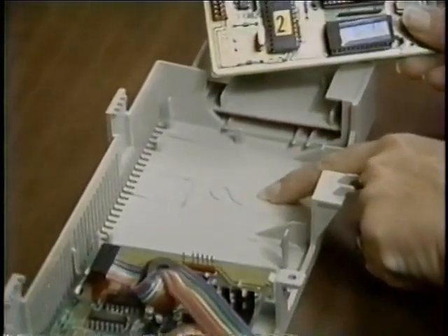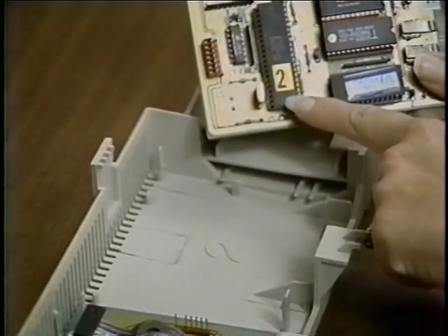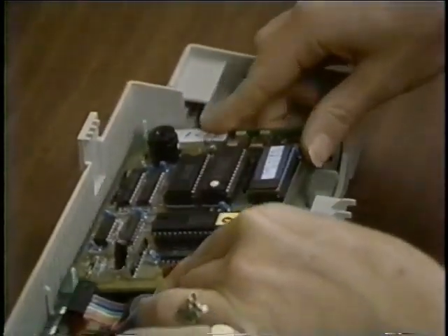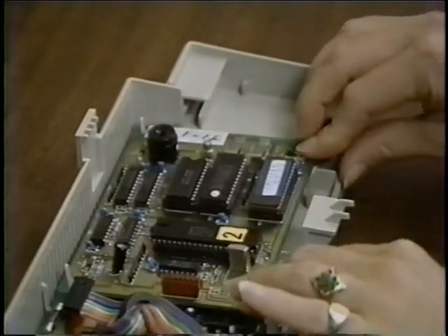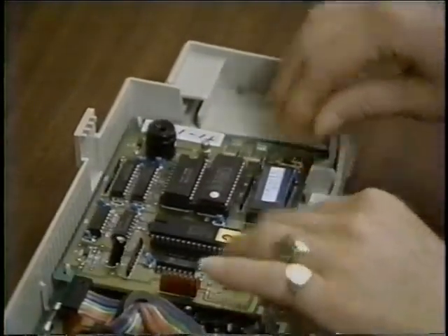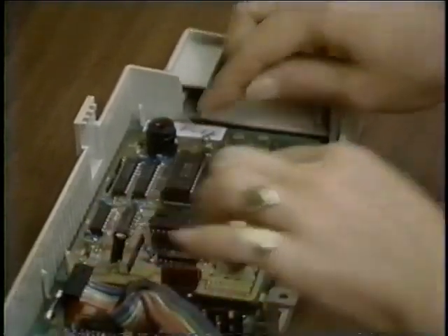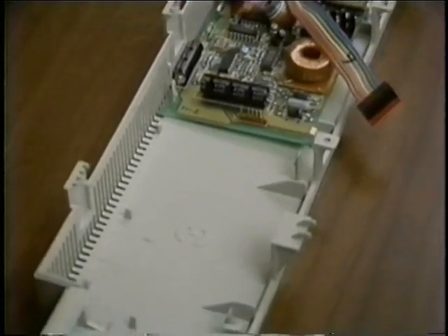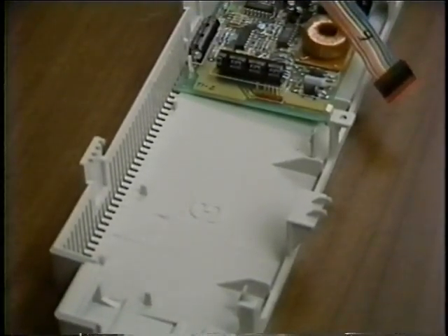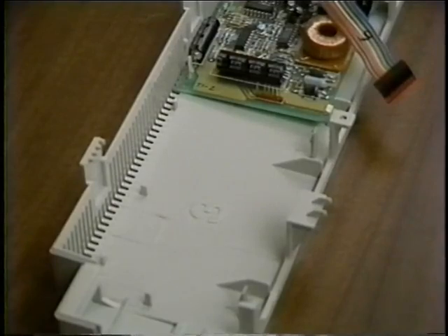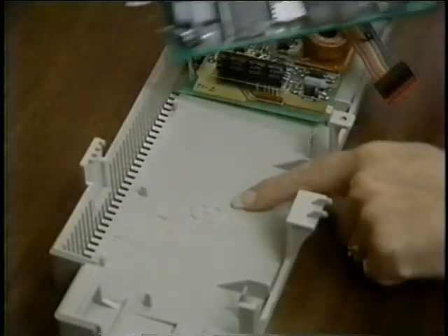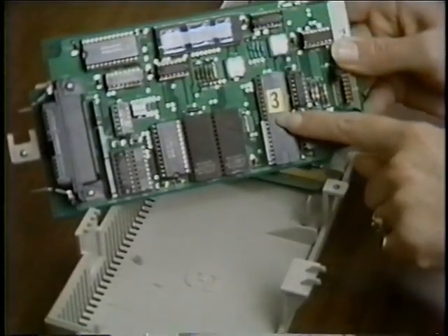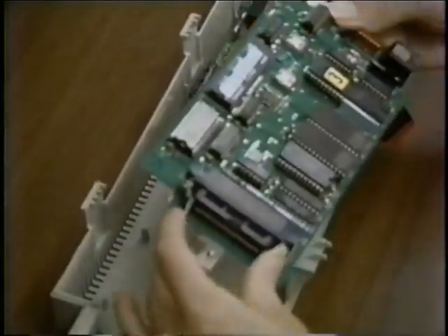To install the spelling verification board, which is board number 2 in the option cover, place it in the side marked 2. Align it so the mounting posts fit through the mounting holes in the board, then press down on each corner of the board to latch the board in place. Board 3 is installed in the area marked 3 using the same method to install board number 2. Remember that board 3 can be the display option, the printer option, or both.